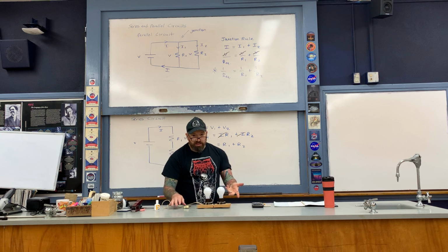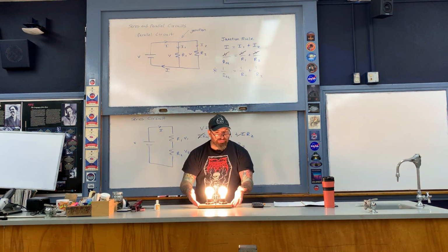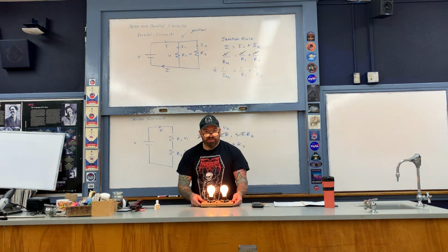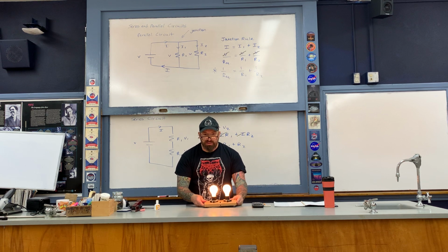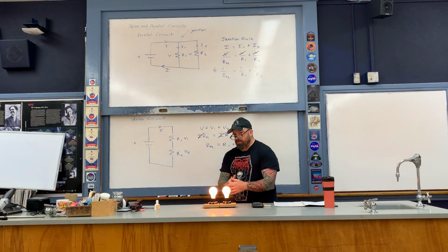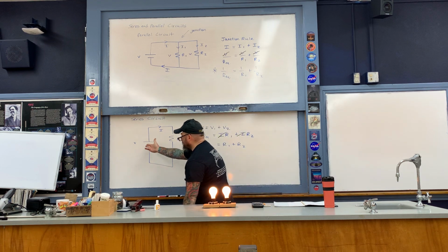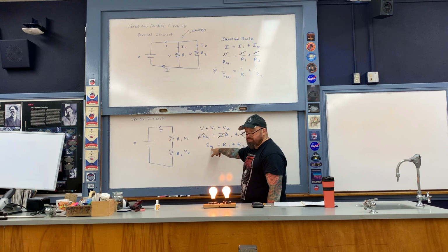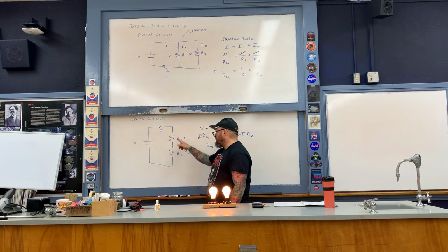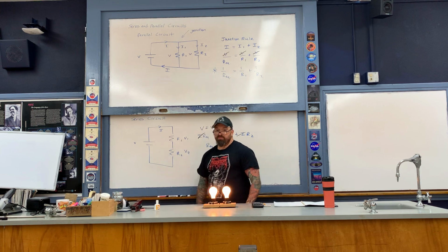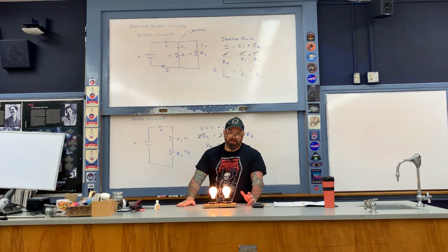Now I can demonstrate that here by means of my light bulbs. Okay, once again, this is when they're in parallel. And then by flicking this switch here, here's the bottom of the board, by the way, when I flick this switch here, now they're in series with respect to each other, and you can see that the bulbs are a lot dimmer. The reason why the bulbs are a lot dimmer is because it's the same potential difference V the whole time, but now I've increased the resistance by placing the light bulbs here in series with respect to each other. So if I place the light bulbs in series, then the amount of conventional current goes down. That's why the bulbs are not nearly as bright as they were earlier in parallel.